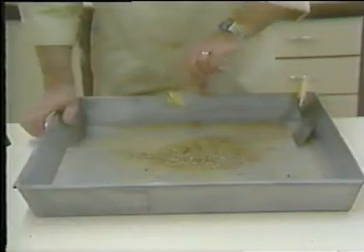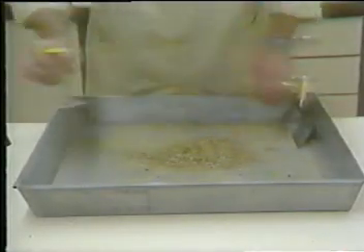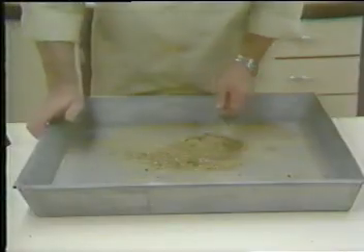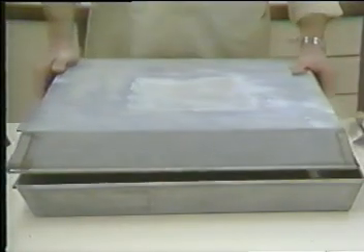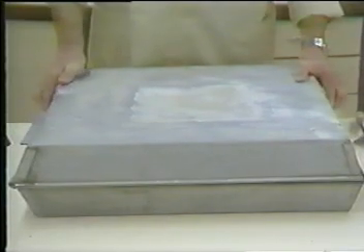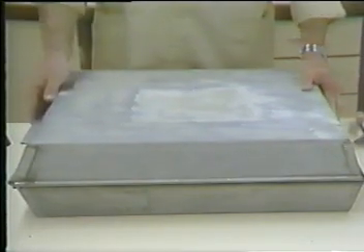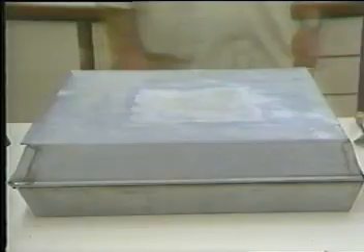If the first cone test indicates there is no moisture on the surface, thoroughly mix a few milliliters of water with the fine aggregate and allow to stand in a covered container for 30 minutes. Then resume the process of drying and testing at frequent intervals to surface dry condition.